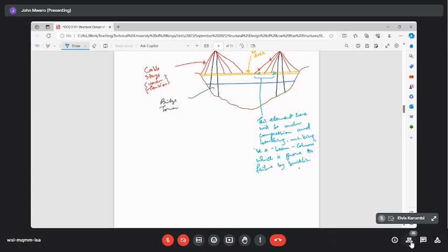Buckling. That's the main concern about this type of structure. So when you design it, you have to ensure that the deck element is not only an element that carries bending and shear, which is what we usually design the beams for the deck for and the slabs for the deck for. If I will have the opportunity to take you through bridge design, I will take you through these thoughts, maybe not in a lot of detail because it's a lot of information, but generally you find that the deck, you want to check it for bending mainly, shear, things like punching.